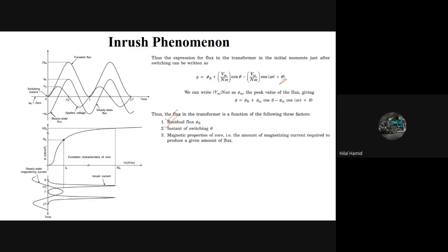So I think the difference between the inrush current and the normal full load current is that the inrush current is not purely sinusoidal. Yes, definitely, it is not pure sinusoidal. It contains harmonics. So what do we have to do? We have some kind of relay which restricts that current, restraining the relay from operating whenever these harmonics are there in the system.